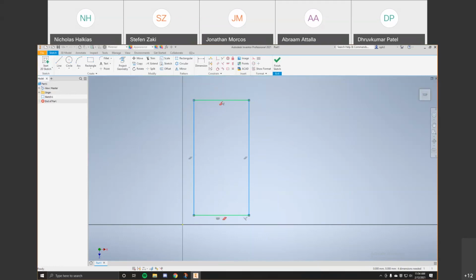That means whatever I do to this drawing, they will always be forced to be parallel. Same thing with these two side ones. And if we look down here in the corner, these two lines will be forced to be perpendicular. So the combination of all these constraints means that no matter what I do to this shape, if I try to manipulate in any way, it'll force itself to be a rectangle, a perfect rectangle.